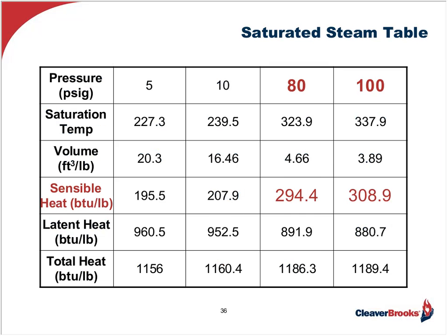Now, before moving on to the selection of the major components for the deaerator, I think I would be remiss if I didn't come back to capturing all the condensate we possibly can, as this is truly liquid gold. On the screen now, I've returned to the steam table just to re-emphasize again how much sensible energy goes into each pound of water as we increase pressure before arriving at saturation temperature.